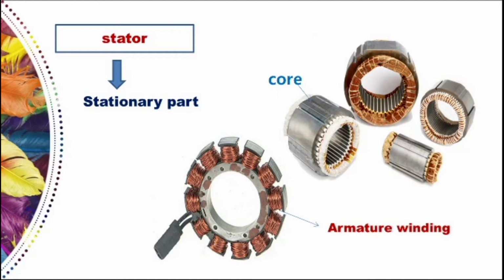What is this stator core? It is made up of iron ore, steel alloy. It is a hollow cylinder and it is laminated to minimize eddy current loss. Dear students, we have learned the meaning of eddy currents in previous videos, isn't it? Eddy currents are undesirable. There will be loss due to the eddy current. It should be minimized. How is it done? By laminating.